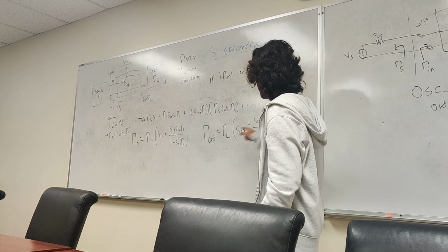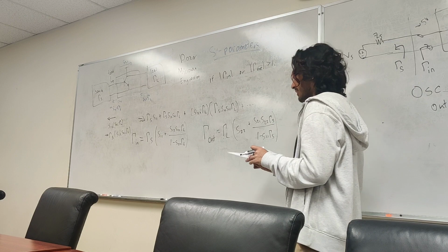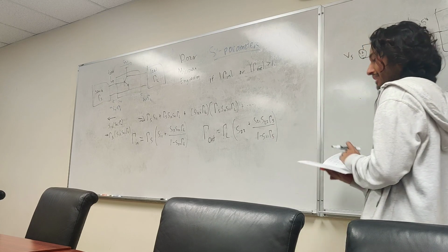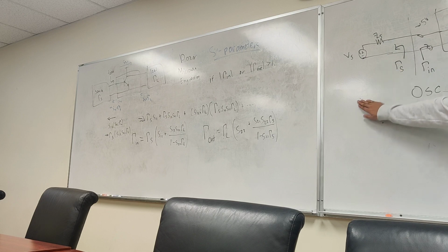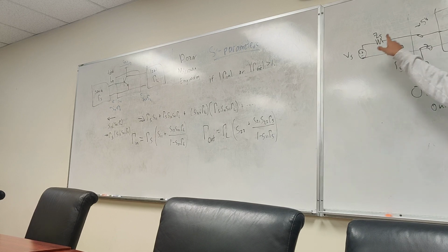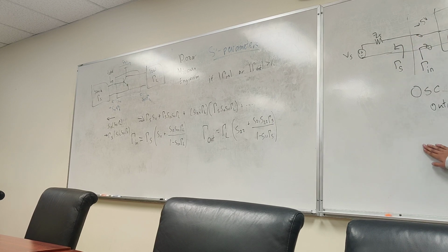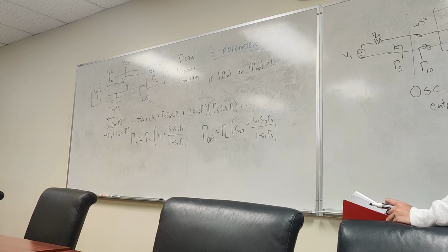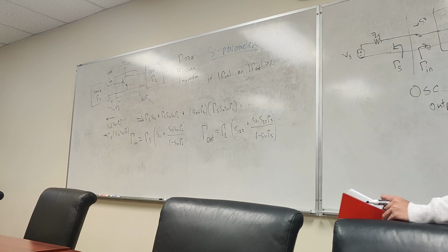This means that what determines if we oscillate is determined by gamma S and gamma L. It's how well we are matched between this and our BJT. So sometimes we can get oscillation just by plugging something in, with reflections and everything. That's something to be aware of. Based on how this matching is, if we don't match correctly, we can get oscillation.